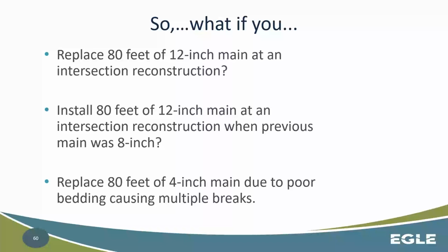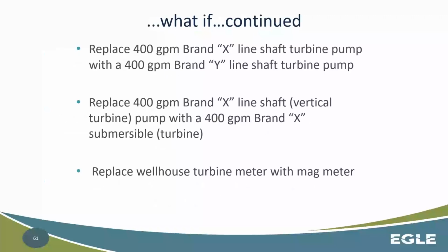Though this might not necessarily need a permit, I would still probably recommend that you go through EGLE, just because in most circumstances, I would argue that 4-inch water main is probably inadequately sized. So not everything's a slam dunk, and it doesn't hurt to reach out, and it doesn't hurt to submit a permit either. Again, they are free. Maybe it adds a little bit of time, but overall, I highly recommend sending something like that in, or at least giving a call to your district engineer.